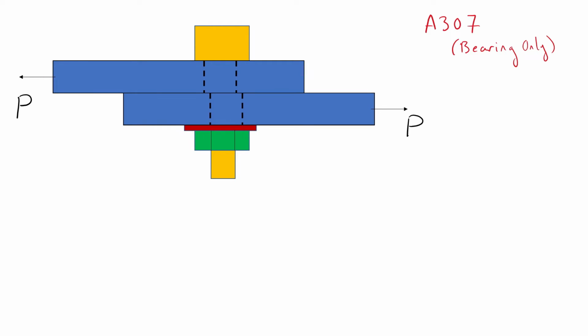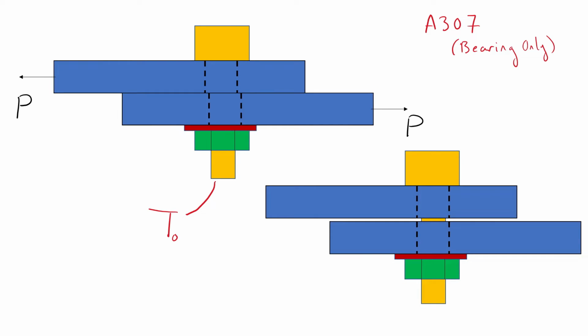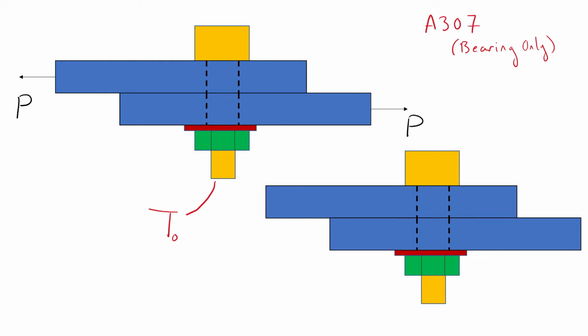Proper installation and achievement of the prescribed initial tension is necessary for slip-critical connections. In bearing-type connections, the only practical requirement for the installation of the bolt is that they be tensioned enough so that the surfaces of contact in the connection firmly bear on one another. This installation produces the snug tight condition referred to earlier in the discussion of the turn of the nut method.